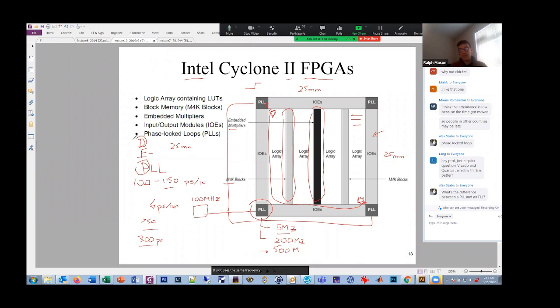So the PLL is kind of the best of both of these. It gets the phase alignment of a delay lock loop, and it gets the frequency multiplication ability of a frequency lock loop. So these are more commonly used than anything. And I always tell students, if you ever want to learn something in your undergraduate, learn as much as you can about PLLs, because they're in every digital chip that people make today, and they're in every analog chip or mixed signal chip, because they're so powerful to do these kind of things.